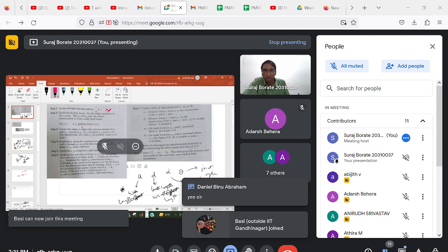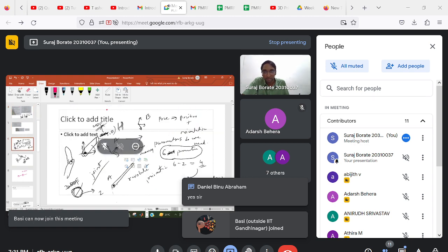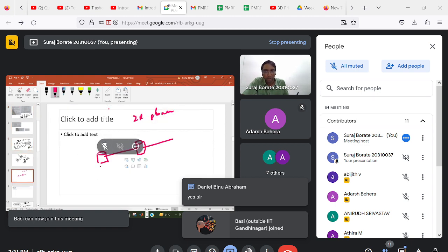The first step is to locate and label the z-axis. So this is joint 1 and we label the z-axis. I will use a different color for each axis. So let's say z0, z1. If there was a prismatic joint, we would have put z2 on the axis of the prismatic joint. So we just have to blindly rotate and label all the z-axes. Now the second step is